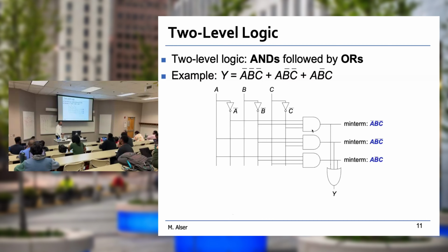So if I ask you to draw these, please all the time use this method. Unless it's a really simple circuit, like 3 gates, 2 gates, then it doesn't make sense to propagate. Remember, if the circuit does not use any NOT gate, you could eliminate those gates and their wires. Okay, you don't need them. If the circuit does not use any NOT at all in the equation, really no need to add those NOT gates. Okay? The goal here is to allow to reuse the NOT gate as many times as possible. That's why we allow them to have here, because we already know all the terms we are going to use.